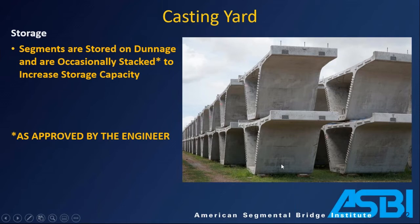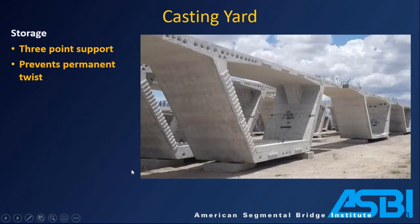So in this picture, you look under the web and you can see two of these sandbag supports underneath it. And as we go to the next picture over here, you see a single sandbag support on one side. So this is really the way that they're always stored. It's this 3-point support. Why do you do that? You don't want them rocking. If you put in 4 points, it's like a 4-pointed stool, and you always have one corner that's a little bit lower than the others.